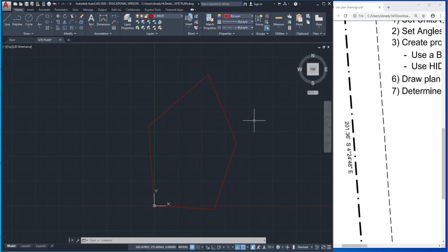been created separately. The next thing we're going to do here, we're going to take this site plan and we are going to scale it up, okay? So if you were a civil engineer, you could likely skip this step because you would just continue to work in decimal inches, right? But if you are an architect and you have been sent this site plan, you need to translate it into architectural units so you can use it, okay? So we are going to change this. We're going to scale it up, okay?